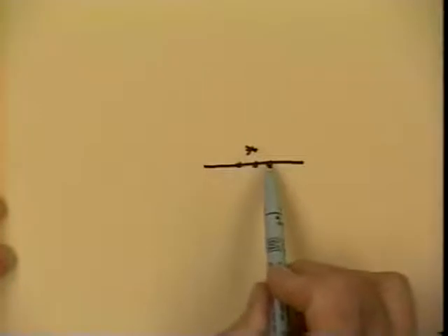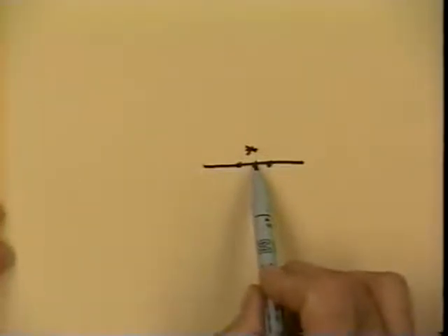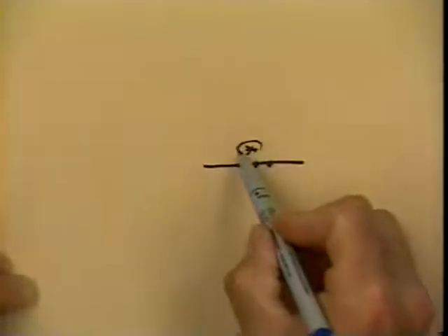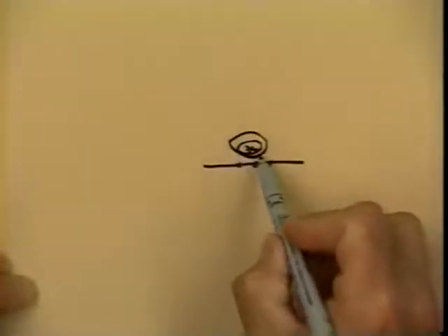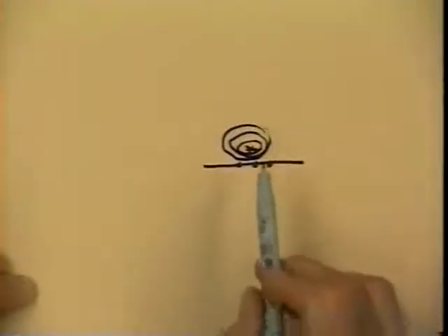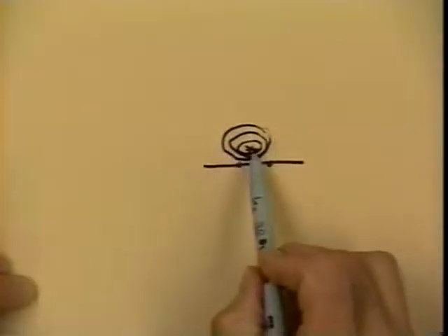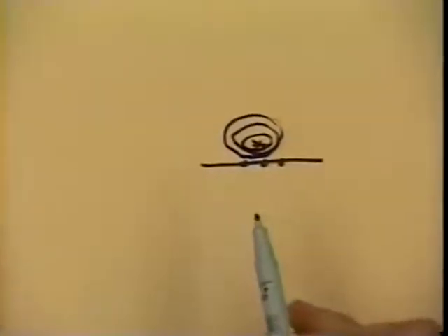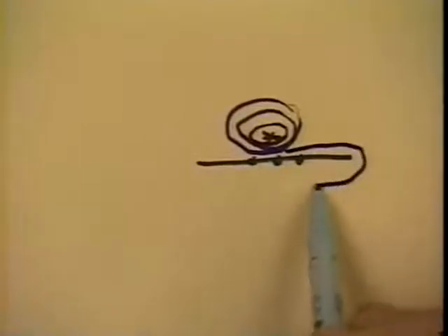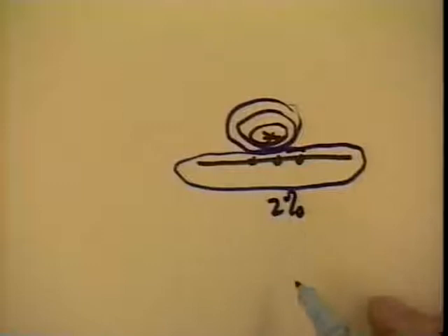Now we said at high frequency the current concentrates mostly right under the trace. But it does spread a little bit. Now if we were to look at the magnetic flux, and I'll draw this in blue, most of the magnetic flux is going to take the short path. That's the path of least reluctance. 98% of the magnetic flux, just as a rough number, 98% or maybe more will encircle the smaller conductor. But a small fraction of this flux encircles the larger conductor. I'm saying maybe this is 2%. It might even be less than that.